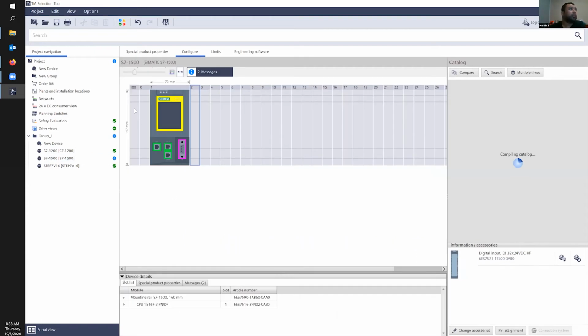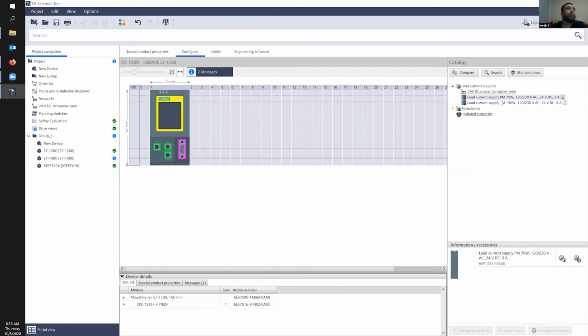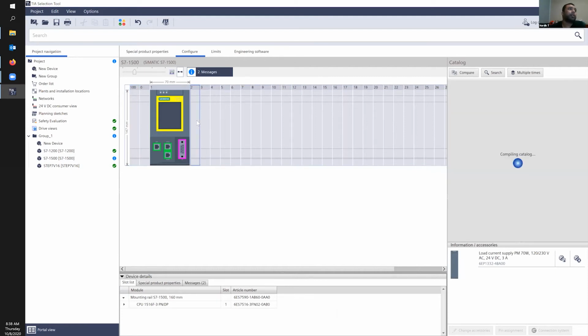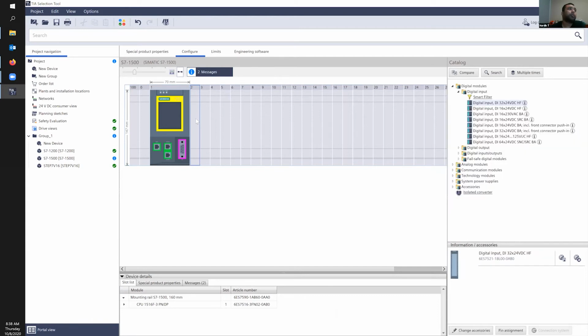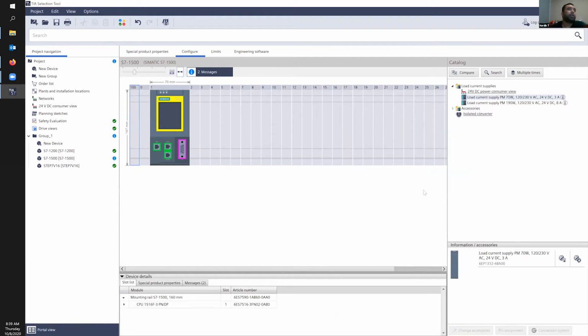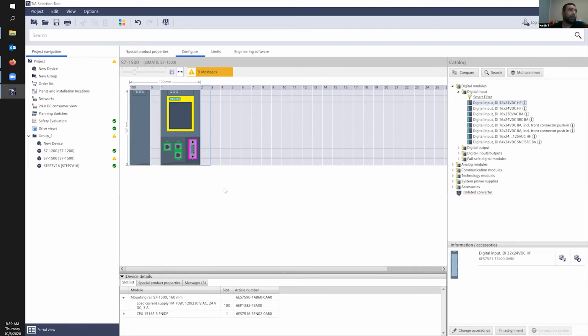The other thing here is for the 1500, if you select and click on this 100, see how it changed on the right hand side. So it knows, it's cursor sensitive. Wherever you have it clicked, things will change on the right hand side, just like it changes in TIA Portal. So there are different power supply options. There's a good thing about this power supply that I usually put in. It's got a little toggle switch. So in case you want to just power cycle your PLC and not have anything else lose power, then you can just toggle this switch and 24 volt to the CPU and the IO cards will reset. And then you can reset your CPU.